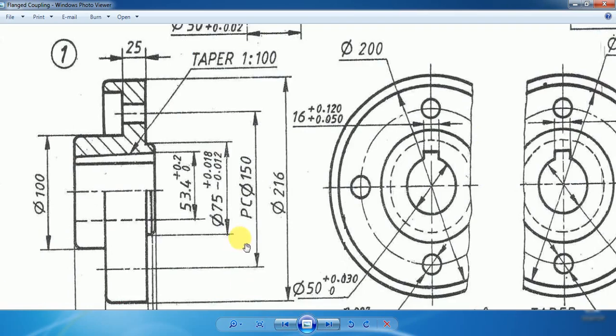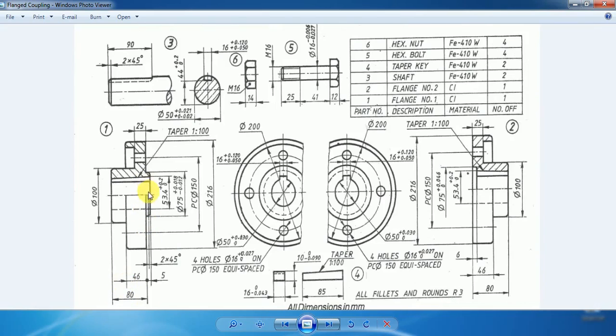Okay, and then what we need to do is we should go for giving the taperness here. So what is the overall length? Overall length is actually 80 plus 5, that is 85, means the distance from here to here is 85. If we move from right to the left for a length of 100 mm, the reduction in height should be 1 mm, but here we are moving only by 85 mm, which is less than 100, so therefore the height should be decreased by 85 by 100, that is 0.85 mm.